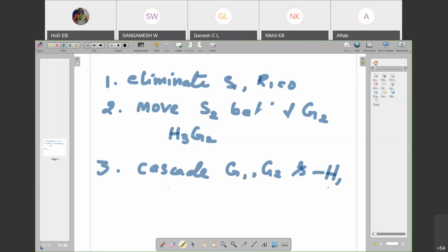So draw the block diagram having one block minus G1, G2, H1, applied to the summing element S2. Okay.